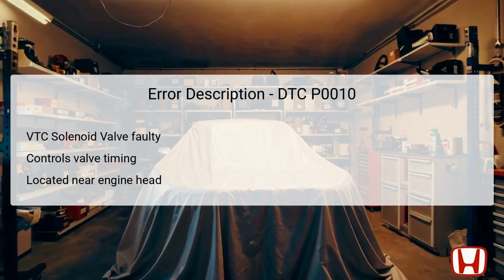If the DTC P0010 is triggered, it indicates a significant problem with this component that must be addressed immediately to avoid severe engine performance degradation and potential damage. This malfunction can arise from operational factors such as excessive dirt or oil contamination, which may hinder the valve's movement.